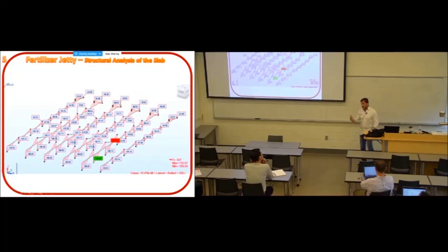And here I want to open a parenthesis. Correct me if I'm wrong. Whenever you have a solid slab, don't worry about shear. Worry more about moments, because to break a solid slab in shear, you need very high, concentrated loads, to have punching, maybe. So I checked shear here, and we are very safe, even with all these high loads, 15 tons per square meter.